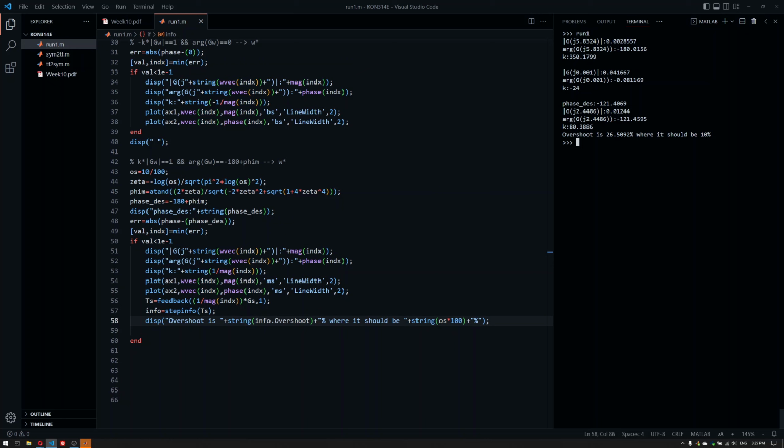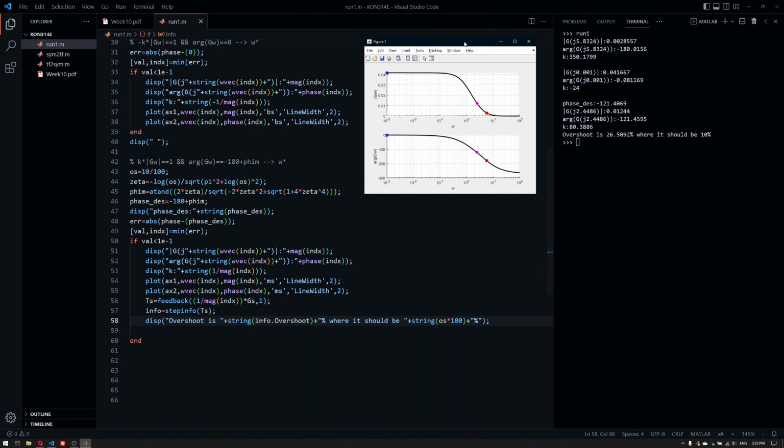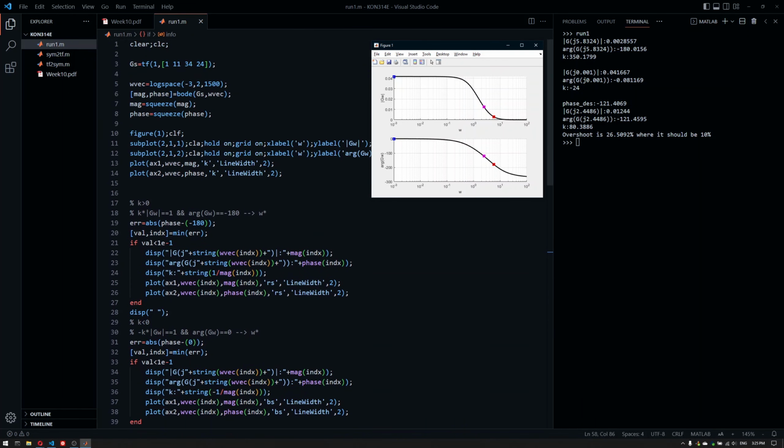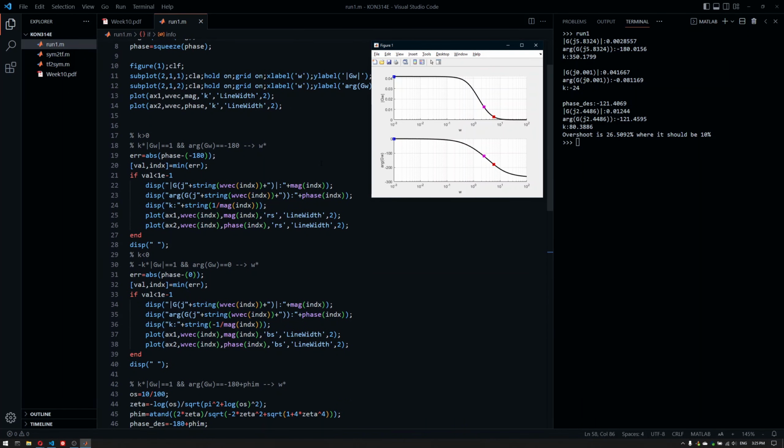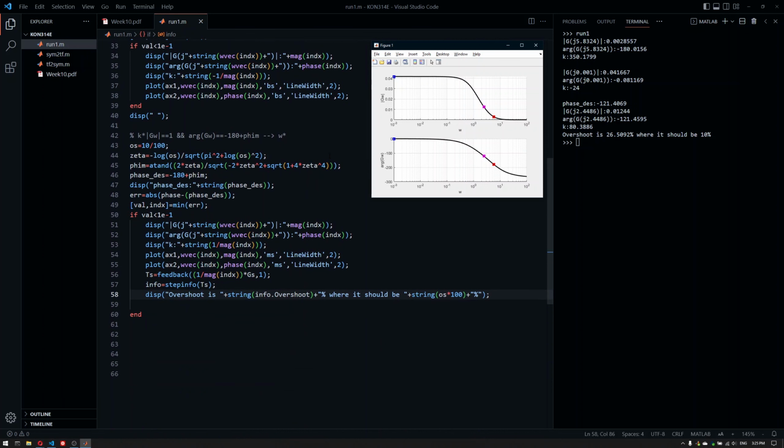And here, again, the reason is that we basically have a third order system. If it has some delay in it, or other things that are not modeled using zeta and omega n, because zeta and omega n is just a way of defining a second order transfer function without a zero, an all pole transfer function, then these differences are expected.